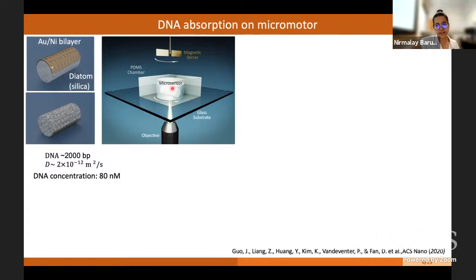How did you fabricate the PDMS well with a diameter of 30 micrometer? You just need to get a mold, a silicon mold with a pillar of 30 micrometer diameter. Then you pour the PDMS onto your mold surface and peel it off.